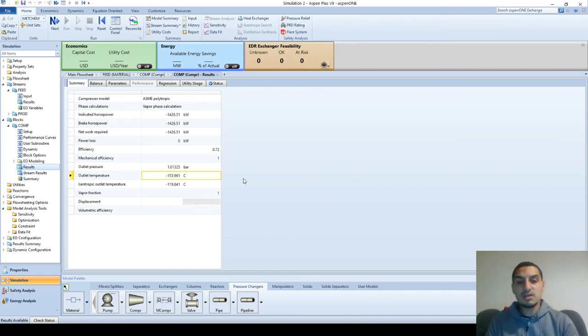This is because the refrigerant, which is Freon or whatever its name, is being compressed using a compressor, and this is what consumes the energy in the fridge or in the freezer. You're applying a lot of work to compress it, and then the liquid is suddenly throttled, and this results in a very big drop in the temperature, and that's why you can get the freezer to work.